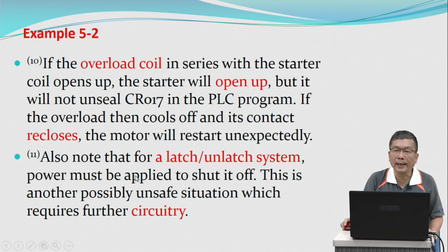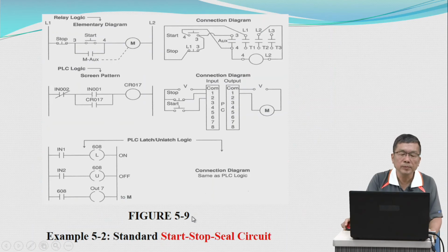Also note that for a latch-unlatch system, power must be applied to shut it off. This is another possibly unsafe situation, which requires further circuitry. This shows the standard start-stop seal circuit. Start, seal. This shows the latch-unlatch scheme.